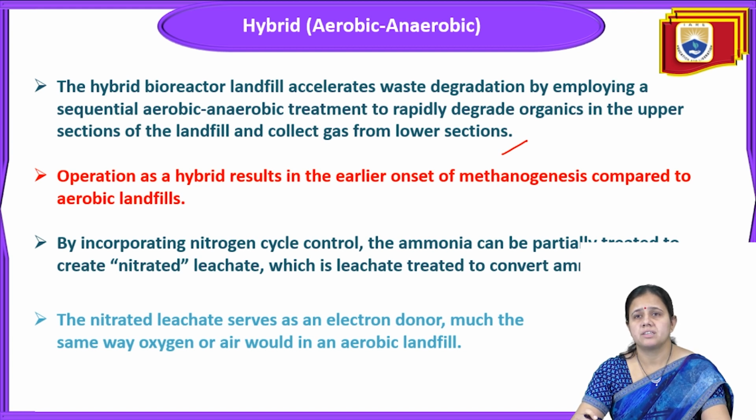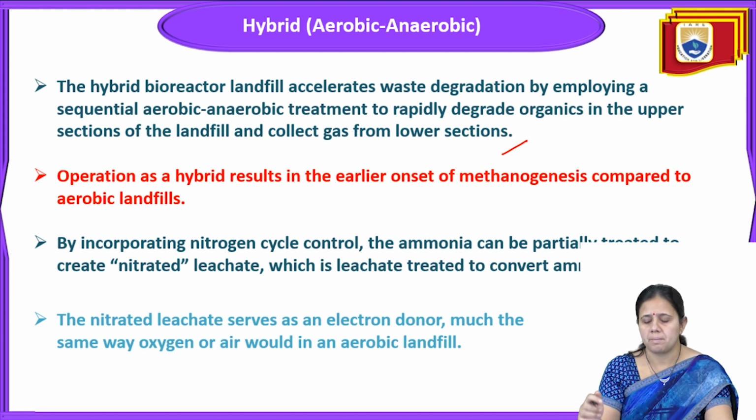The hybrid bioreactor landfill will accelerate waste degradation by employing a sequential aerobic and anaerobic treatment to rapidly degrade organics, so the organics and suspended solids present in the leachate can be reduced.